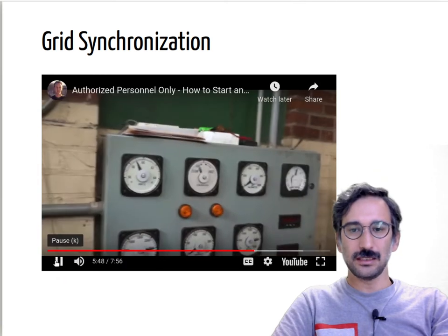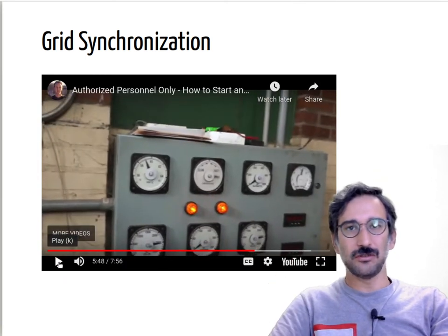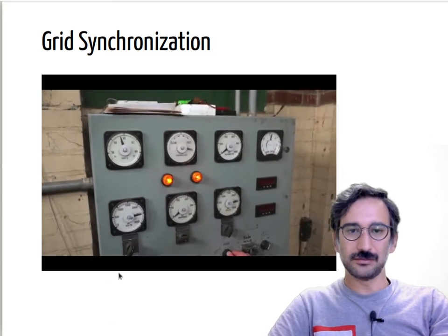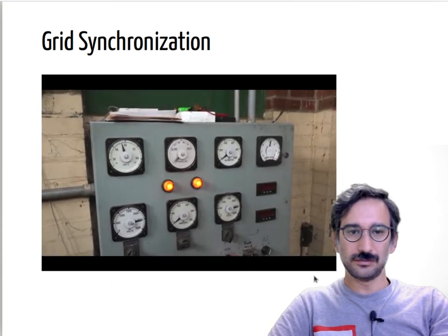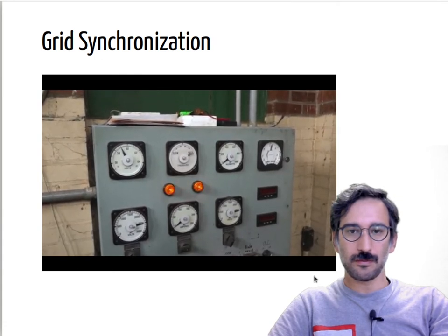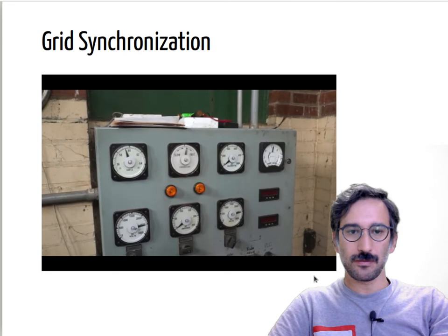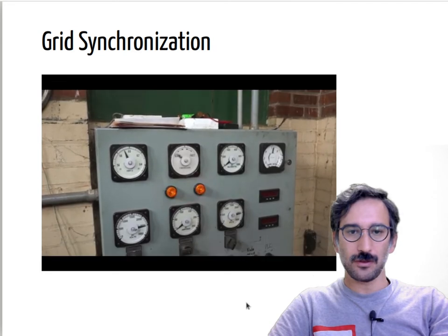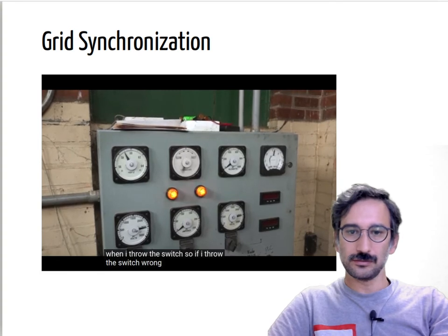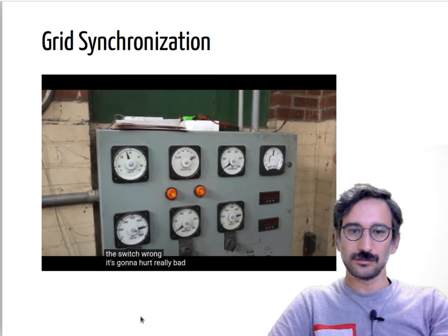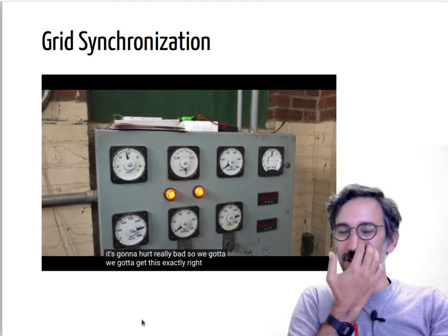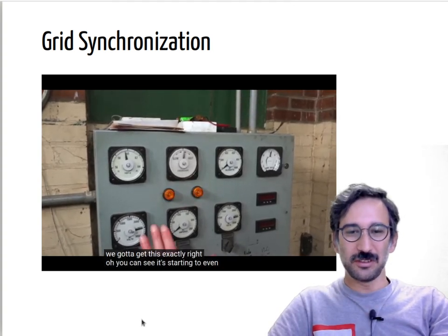But look at the frequency of those lights as it gets faster and faster. Very big, expensive, angry sounds, because that giant turbine right behind me will synchronize to the grid no matter when I throw the switch. So if I throw the switch wrong, it's going to hurt really bad. So it doesn't want to. So you want to make sure everything is correct before synchronizing.